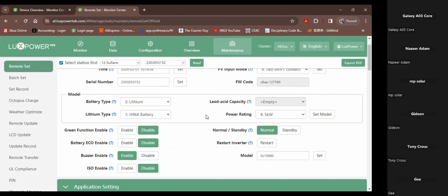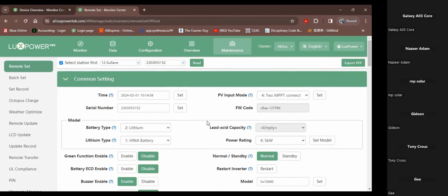But eventually, as you know, not all of the occupants of the home are aware of this, and somebody will invariably plug in an iron or a toaster or a hairdryer or something, and the inrush current will trip it, that sets the battery into alarm. So always when you're speccing an installation with an SNA, remember this inverter is not tolerant to weak batteries.